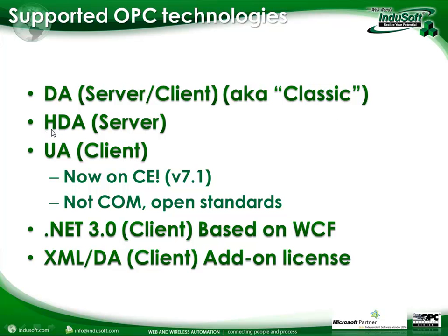We can also be an HDA server. We can be a UA client, which is something relatively new for us, and I'll go through some of that as well. And now, as of version 7.1, we are able to be a client not only on a PC and server environment, but also on Windows CE. And as I understand it, Indusoft Web Studio is the first to have that available on the market.